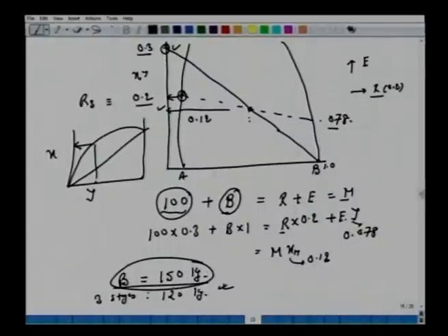All right. So this example we have chosen for this lecture is for cross current 3 stages, where we added fresh solvent at every stage, and we were asked to identify the different compositions. We drew the equilibrium curve. We said that we can solve graphically as well as mathematically. But we have to plot both the y versus x diagram, equilibrium, and the rectangular coordinates, fraction of the solvent, and y versus x.